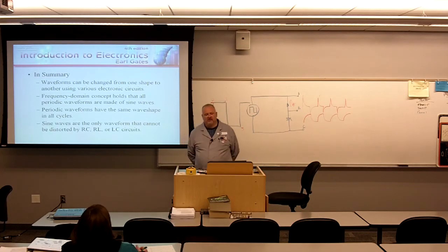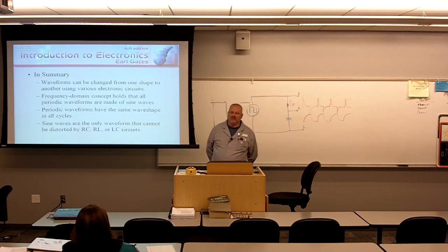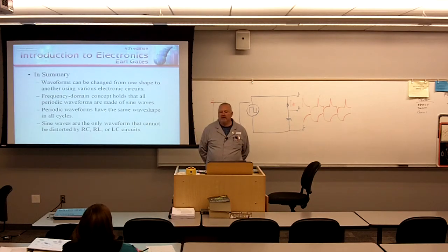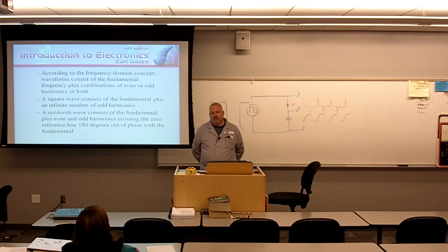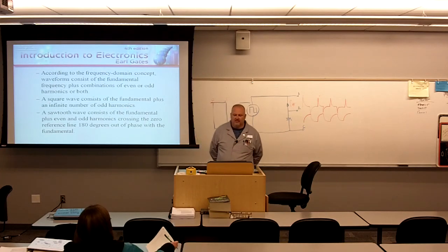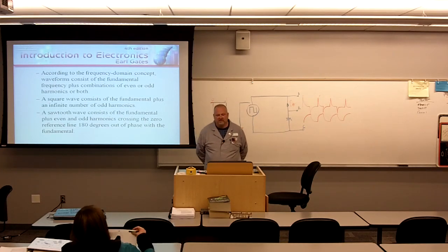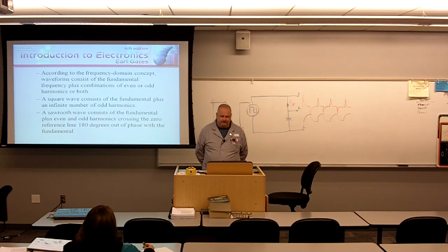In summary, waveforms can be changed from one shape to another using various electronic circuits. The frequency domain concept holds that all periodic waveforms are made of sine waves. Periodic waveforms have the same wave shape in all cycles. Sine waves are the only waveform that cannot be distorted by RC, RL, or LC circuits. According to the frequency domain concept, waveforms consist of the fundamental frequency plus combinations of even or odd harmonics or both.